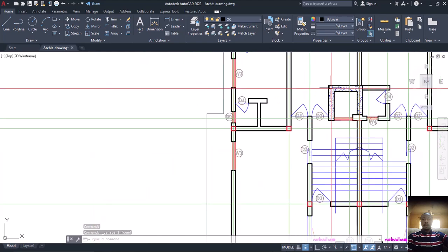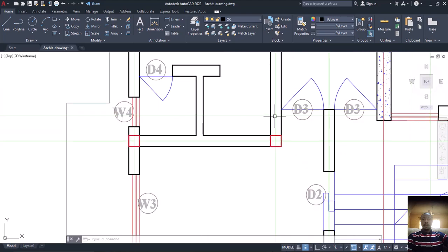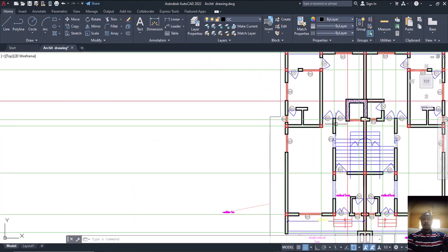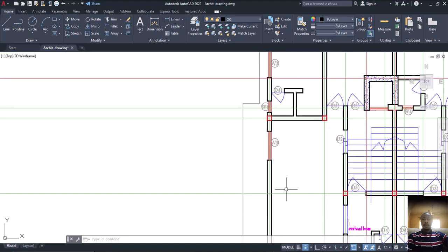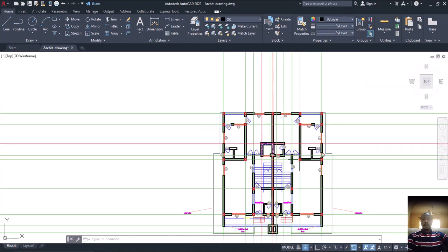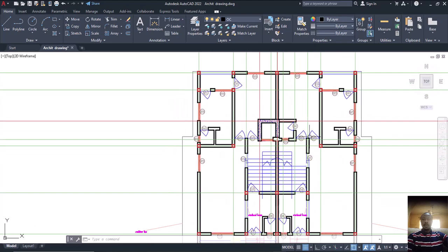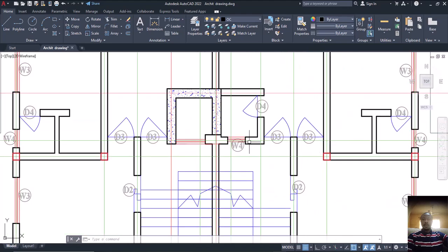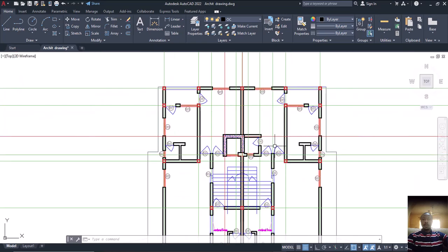Definitely this one, I must have put a wall. Am I correct? I must have put my wall like this here, isn't it? So definitely my beam will run from here to this place. If my beam is running from here as secondary beam to this place, automatically this one will now come and rest on it, which makes this place close, isn't it? So I now have this place more as slab, and the same thing is applicable to this place now. If I now have my secondary beam run like this to this place also, isn't it? And this one will also come to do what? To rest on it, isn't it? So that is that.